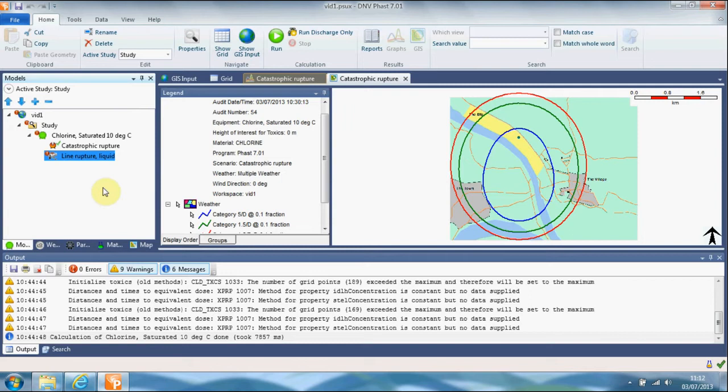We will now supply the tank shape data for the pressure vessel. The settings described above will complete the mandatory input data for the scenario, but when you close the dialog, you will find that scenario is still shown as incomplete in the study tree. So if you hover the mouse over this symbol, you will find that a tooltip appears saying that the tank shape is missing. The tank shape field is actually part of the input data for the pressure vessel, and it becomes mandatory if you have any time-varying scenario present under the vessel.